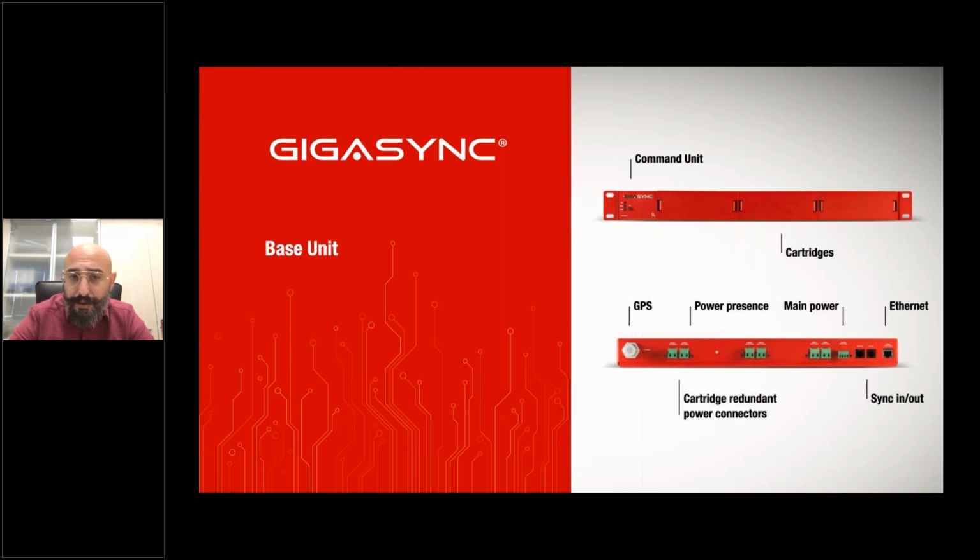It's very useful because you don't need to open your web interface or your management interface to see if there is power or not. Just see the LED. And the main power to the unit can be given with the main power connectors, redundant, and through PoE. Also, the GigaSync is PoE powerable.